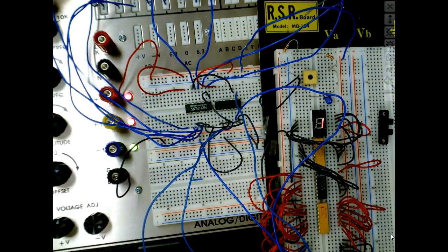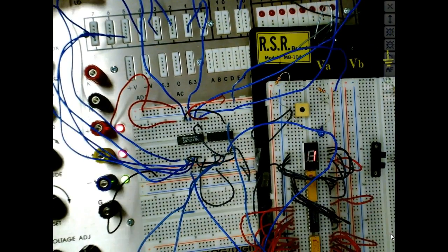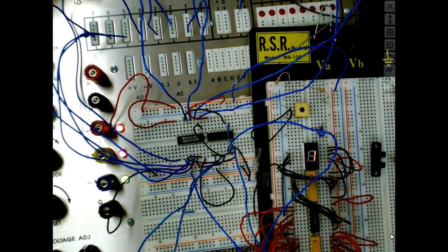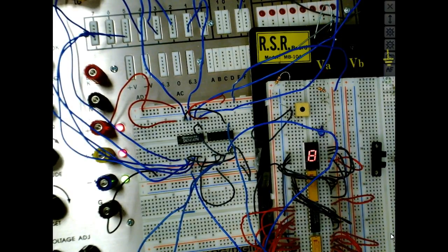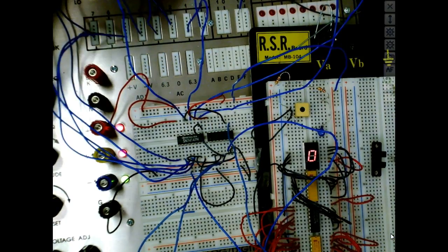Now notice, I'm going to come up here and flip these switches. So I'm going to flip this one. Now why? I still have the 1 on because it's a priority encoder too. So the 8 has a higher priority than the what? Than the 1. Y'all understand that? I left the 1 up there. See that? Okay, here comes switch 2. So what should it do when I put input 2, when I bring it low?